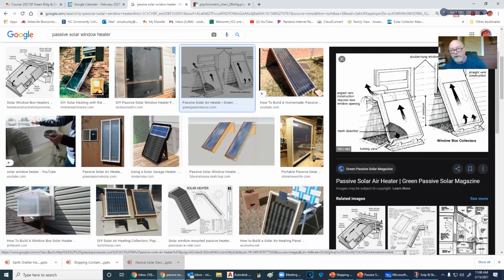You see this mesh absorber. This is a heat absorber in here that's generally black. And I've had two students build two of these. One of them decided to use tar paper, builder's felt, in this thing. And the other one decided to use petroleum caulk. And I'll tell you what, guys, if you ever talk about off-gassing, holy crap. I was going to say, you don't want that in your house. No, I mean, the builder's felt is nothing more than basically paper saturated with oil, and that petroleum caulk, it stinks, it off-gasses like crazy.